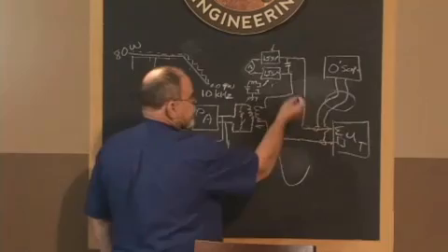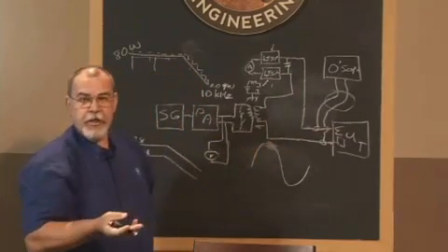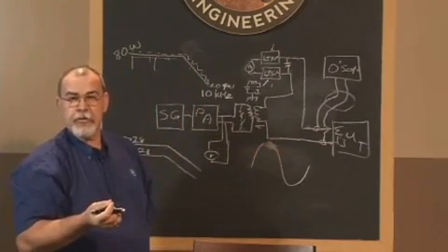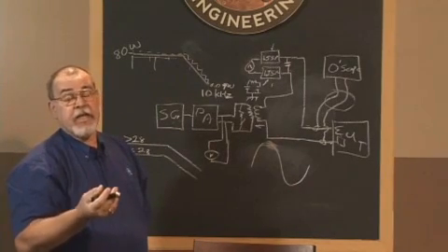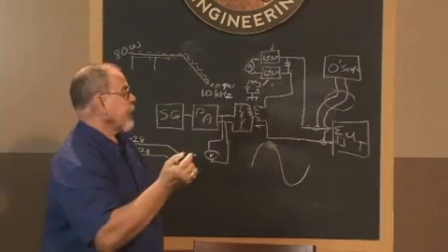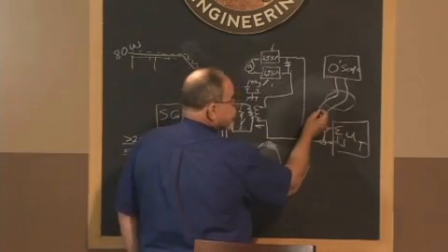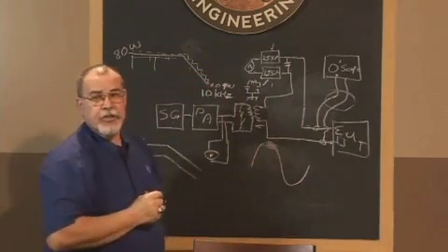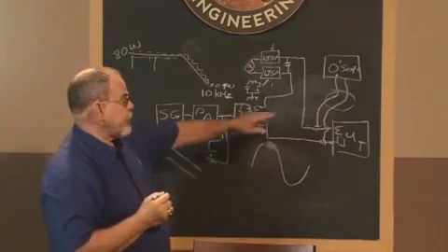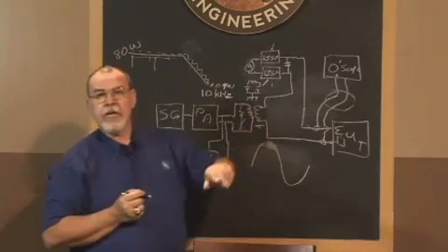However, if this is an isolated power, for instance for Navy applications where they don't use a grounded neutral, or 3-phase power where I'm going to measure between a phase A and a phase C, for example, I have a high voltage appearing on this lead. Well, that lead happens to be the body of the oscilloscope. So if you go up and touch this connector while it's live,